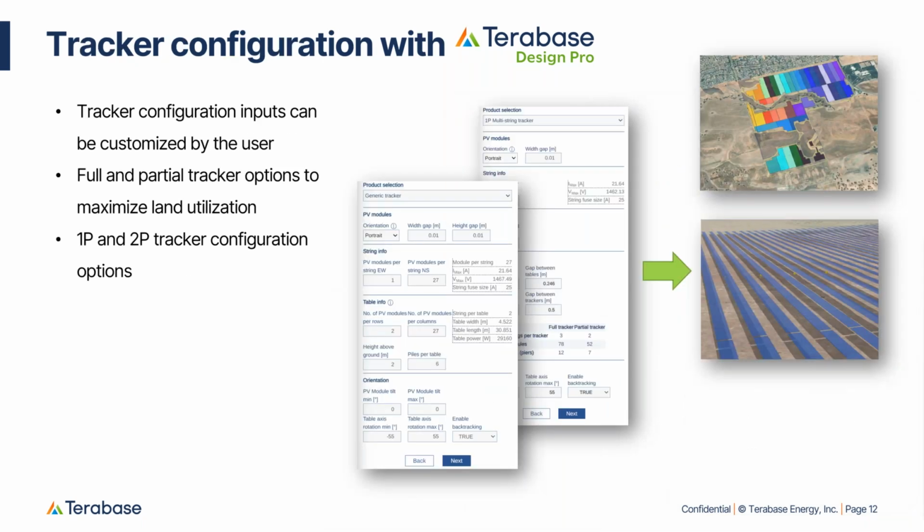When making your racking selection, if you're planning to use a single axis tracker, you can choose between our generic tracker or our 1P multi-string tracker, which will lay out full and partial trackers on your site. Pay special attention to the tracker configurator because there are many parameters that you can utilize, including the tracker minimum pile height and the pile reveal window that will automatically be passed to Terrain Pro for your earthwork assessment.